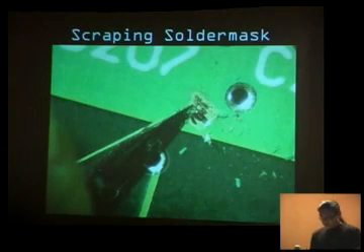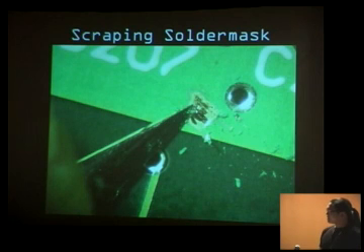So, if you want to solder onto a point, for example here, the solder mats, of course, you can't solder onto. Really, I would just use this via to solder onto, but I had to take a picture of something. You've got to remove this green stuff right here. So you just take a knife and scrape it back until you see bright copper.